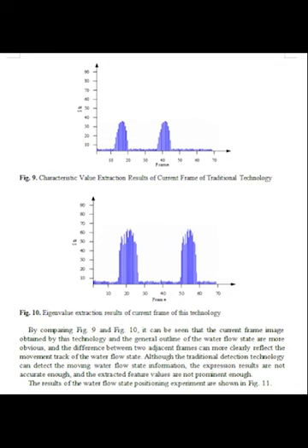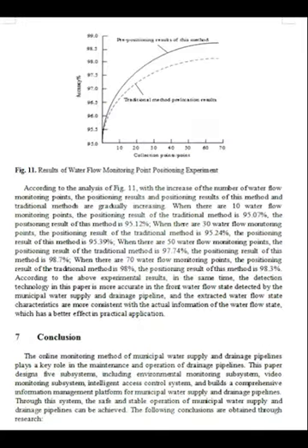First, the online monitoring method proposed in this paper can predict the fault location in 0.45 seconds, and the error of the actual fault location is less than 0.3 meters, and the early warning ability is good.